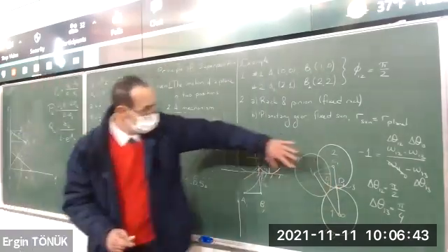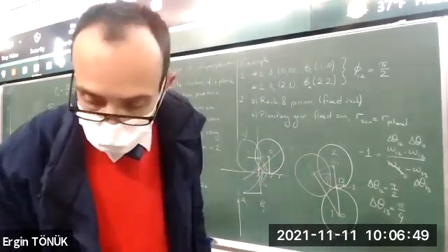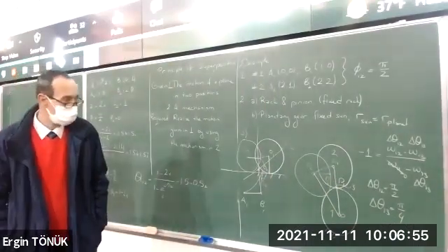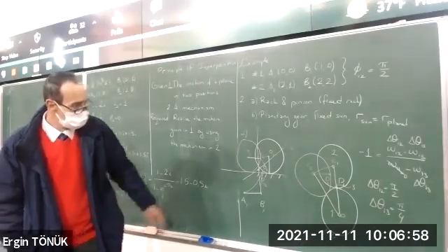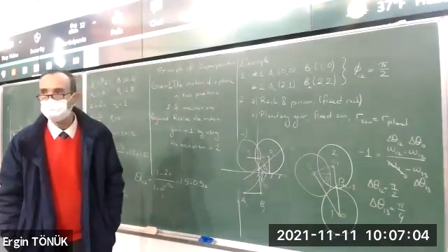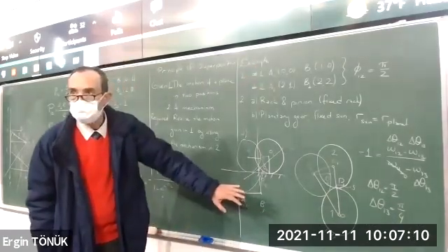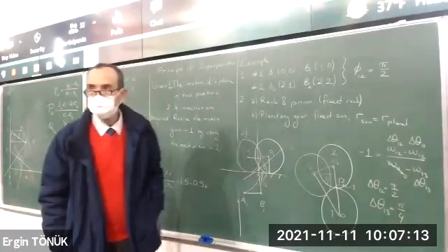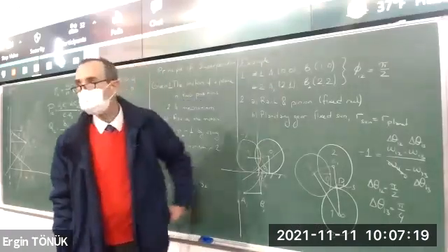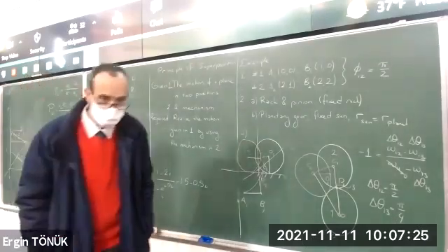Okay, so the planet is going to rotate by 90 degrees. Then, again, you can find the pole either by graphical construction or by using the coordinates of C and D, using any of the formulas we have. We know the pole of this. Coincide the two poles. When you roll it, you will get the same motion. So from A1, B1 it will move to A2, B2. Okay? That's straightforward, I would say.